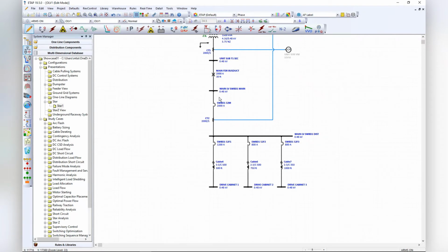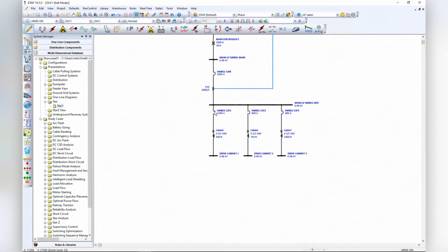Sometimes you miscoordinate with a maintenance switch, and if you leave it on, and you never go back and turn it off, and you don't put it on some sort of delay timer, or you don't put some sort of indication back to some DCS system that it is still on, well, your system is going to be miscoordinated. And maybe you do have a reason why, if this feeder was to have a fault, you might want to isolate it just to that feeder breaker, the 1200 amp feeder breaker. And you don't want that thing to take out the whole switchboard and consequently all three machines. Maybe these three machines are independent processes. So you have to be careful about how you use and abuse that maintenance switch, because I've seen it used and abused all the time.